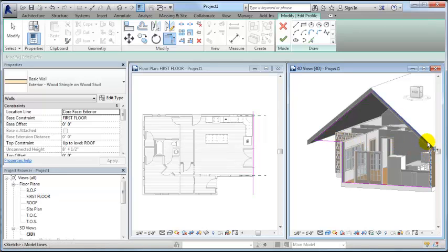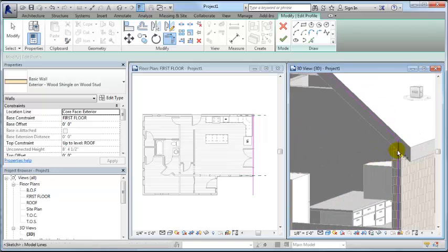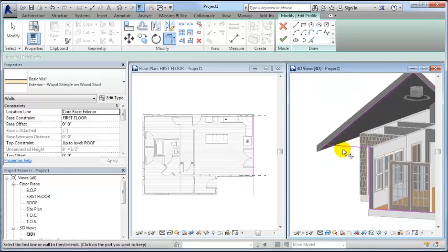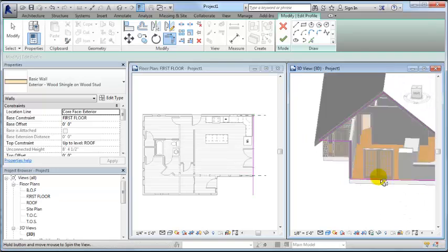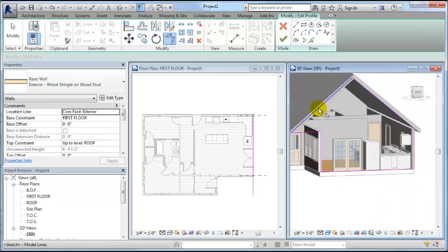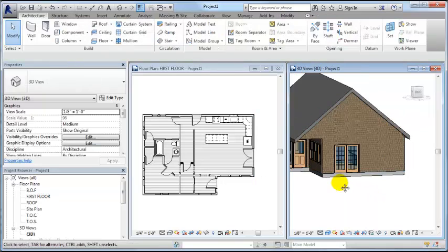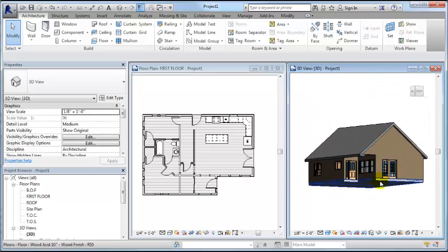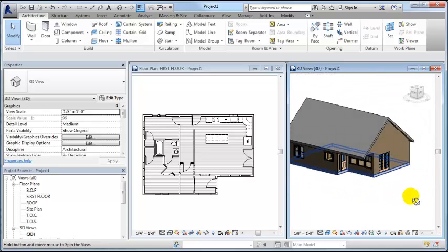And then I want to put these two corners together, and that trims this edge of the line, and I also want to put these two corners together. So I have to trim or fillet those two corners. This one should stay fine, and then I had to fillet those two and those two. Now I've got a boundary essentially that's following the shape that I want the wall to be. When I hit the checkbox, it fills in that space and gives me the house shape that I was looking for.